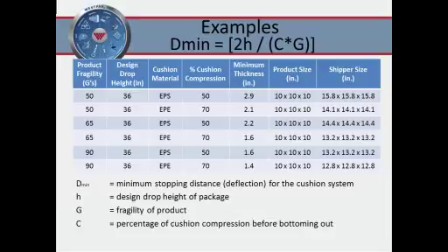It's important to note on this slide, there's a lot of numbers there, but basically what it says is that the product really doesn't know what kind of cushion is around it. It just knows shock. It just knows how much oomph, some impact, some numbers, some severity. And with those given limits, the ones that are shown there, 50, 65, and 90 Gs, there are different deflections necessary to achieve that. Again, the product doesn't know whether it's surrounded by styrene or urethane or Ethafoam or God knows what all. It just knows shock.